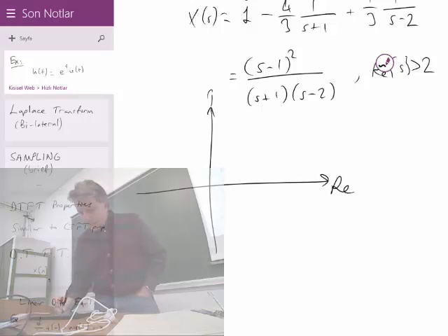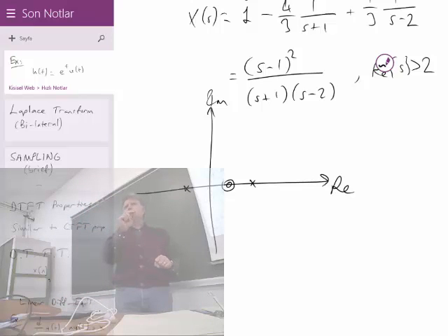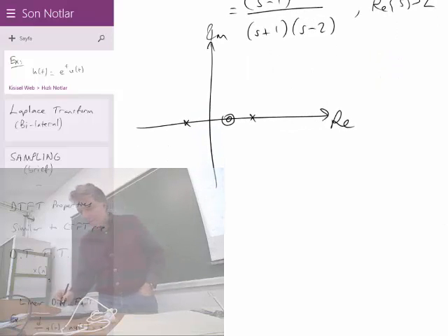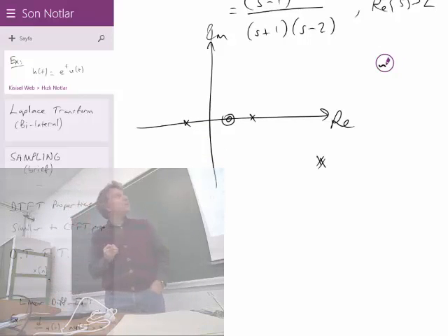Along the real and imaginary axes, let's first indicate the poles. They are at 2 and minus 1. And at 1 we have two zeros. Usually they draw two circles on top of each other like this, just to indicate that there are multiple zeros there. There may be multiple poles as well. If you have multiple poles, it's a bit more difficult to indicate them. I prefer to indicate it like this, for example, two crosses very close to each other. The number of poles and zeros is important; it's just a notation that I'm using.